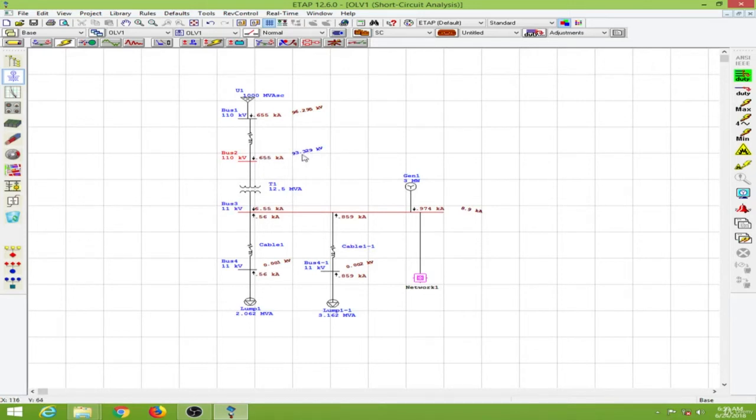The voltage drops at this bus to 93.329 kilovolt, and over here to 96.295 kilovolt, and this is the fault current. In order to get the fault level, we will have to use the pre-fault voltage and the post-fault current. Here the pre-fault voltage is 11 kV, so we will have to multiply the 11 kV with that of 8.9 kilo amps to get the fault level.